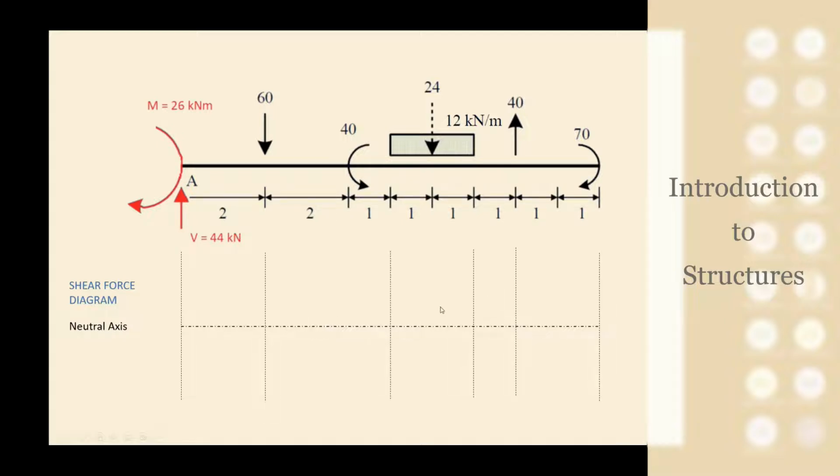So once we have these references, remember that it's a very good practice and it's extremely important actually to read this properly, that the diagram is aligned with the structure. So we need to use the same scale for lengths in the scheme and in the shear force diagram and the bending moment diagram after. So we will usually start from left to right. This is the way I like to do it. You can do it from right to left if you want. But for me, it's simpler if I do these diagrams from left to right.